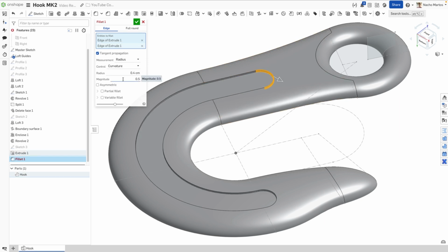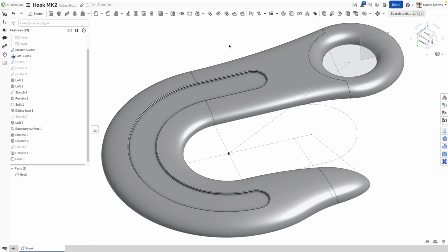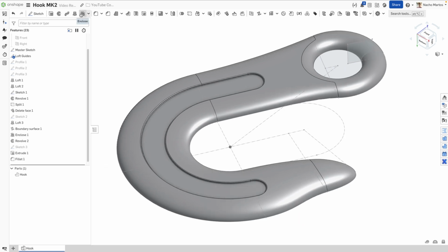Now that we're finishing with detailing, let's just apply a quick fillet to these faces. If you want both faces to have a fillet in them, it'll have to be a relatively small fillet so that it doesn't error out. We'll go to 0.2. That's most of it. From here on out, we just need to mirror our part.